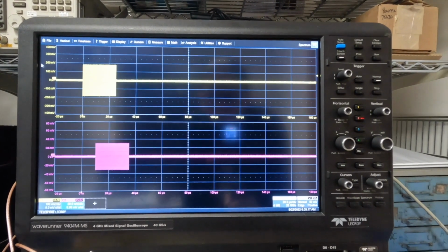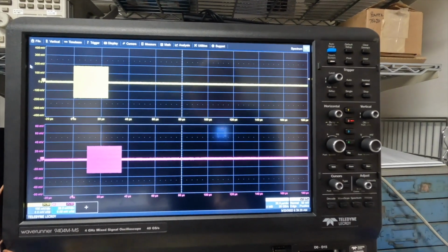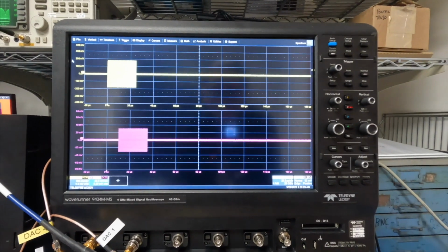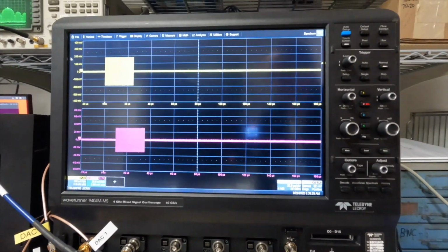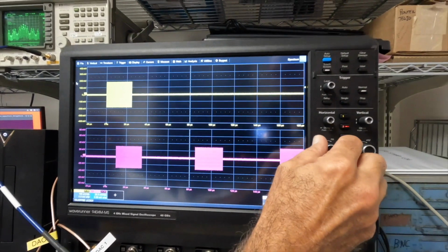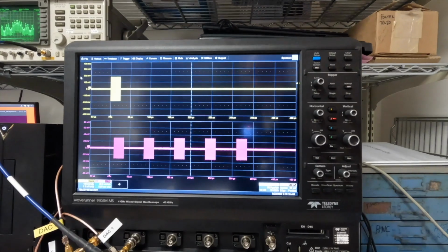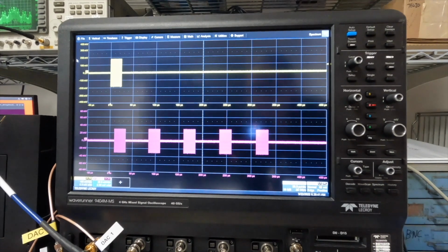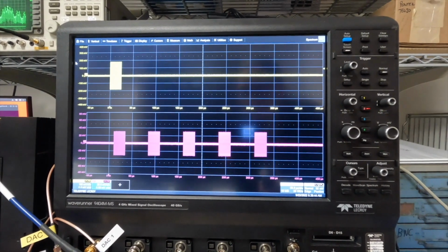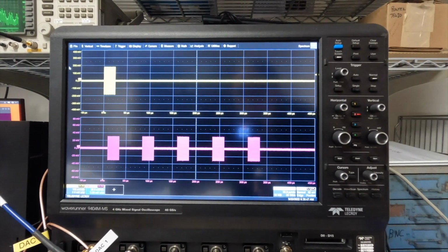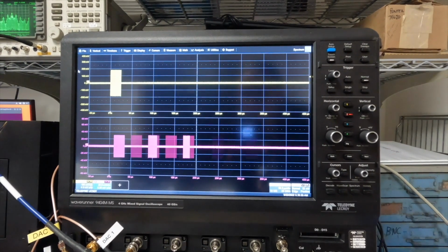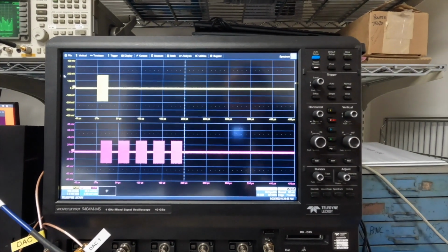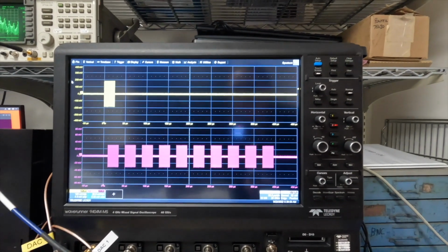Remember, it's a 25 microsecond input pulse with a single fixed range offset, 25 microsecond output pulse, but we're going to up the count to, say, 5 false targets. And if you stay there, we're also going to change the apparent range between the multiple range false targets. And that control will do, say, 40 microseconds from the 25 microsecond pulses. And we'll double the number of multiple range false targets to 10. And we can go back to, say, just 4.